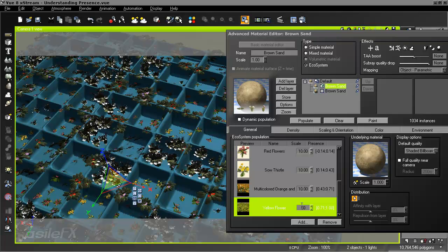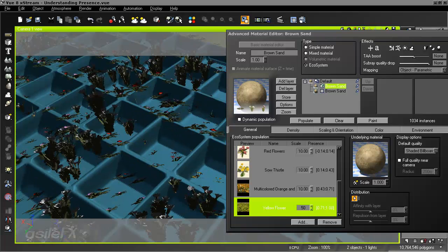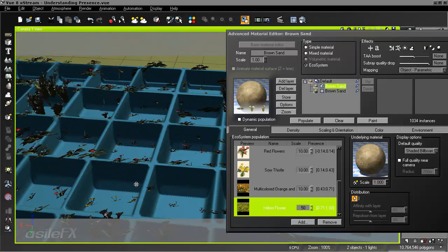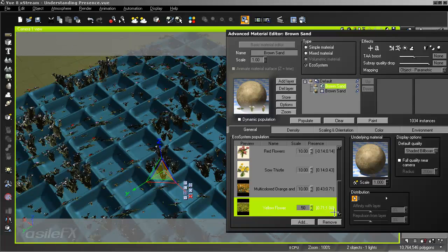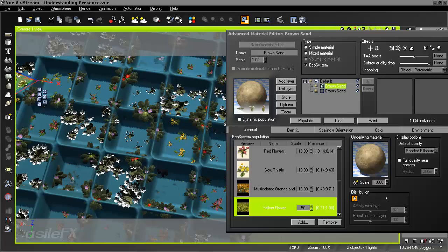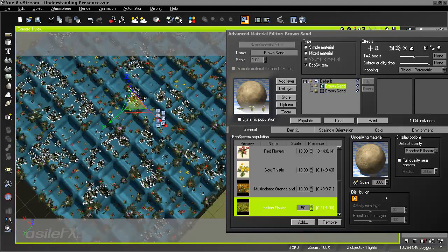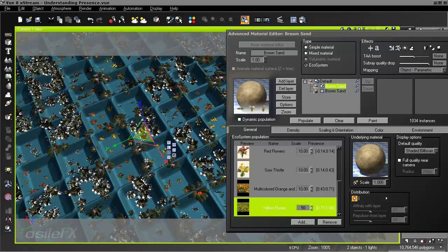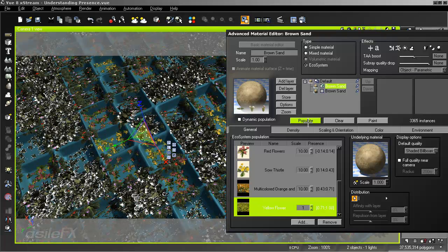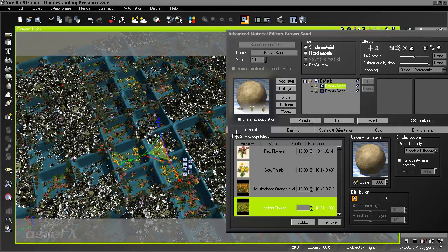You don't necessarily have to use an actual plant or a real object. Sometimes what I'll do is load in a single polygon or a point from another program as an object, and we can use that. The only thing is, if it doesn't have any actual scale, it doesn't always work. So it really depends on the situation. Sometimes you could just use a basic Vue sphere. If you want to have a null object like that, you just got to make sure that the presence is not going to show up within the range, in this case 0.71 to 1. So since the function is not outputting that scale or that number, we're not going to see this item. But it does create a nice little spacer, and we can even take it down the other direction and scale it down to 1, which is now really going to clump things together much closer. So it's kind of a neat thing, a nice little extra control.